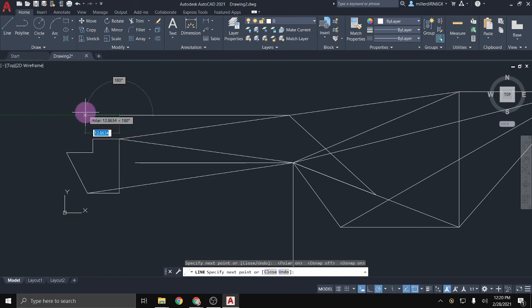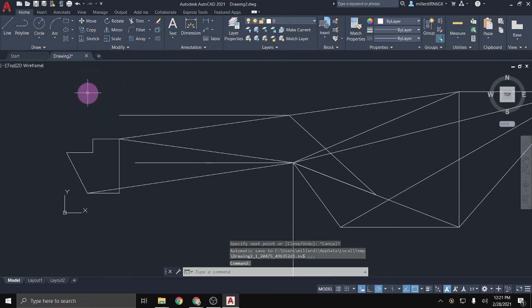And so that can be very helpful in architecture to just see, okay, if I want these two doors to be aligned with each other, I can just figure out where the two pieces would be aligned. And we'll see that in the next video where I go over the demo of the little house project that we're going to practice with. And of course, Escape to end the command.